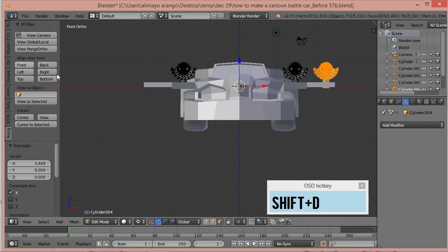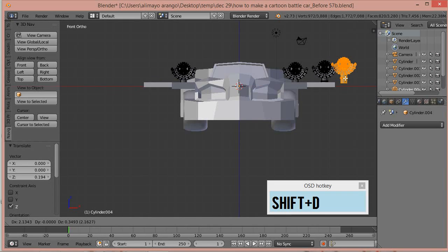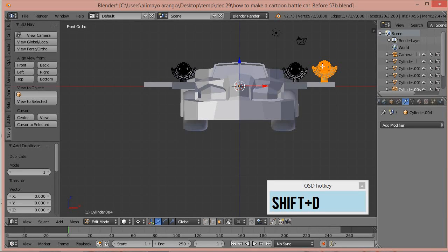We're going to click front view to see how this is looking. We'll push this over a little bit more, push this up some. And now what we're going to do is press Shift D to duplicate this. We're going to right click so it's right back on top of here. But we still have the duplicated cannon type thing selected. So now we have the 3D cursor already centered, and we already have the pivot point set for 3D cursor.